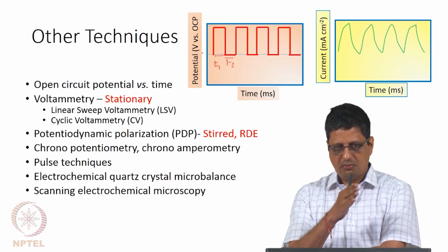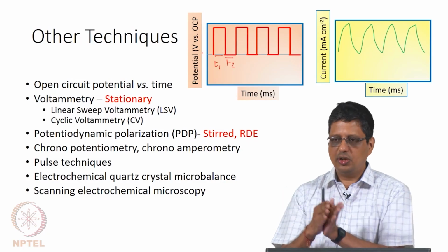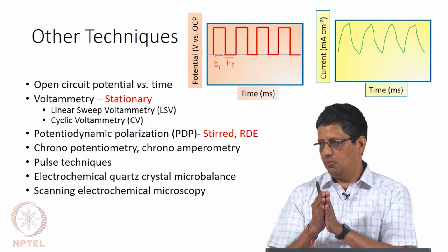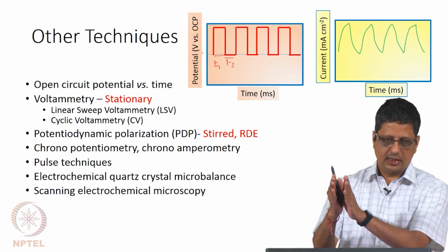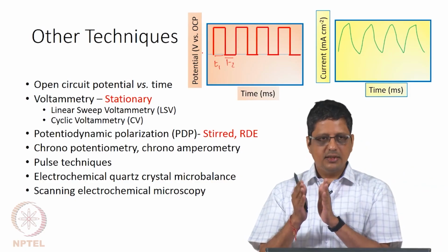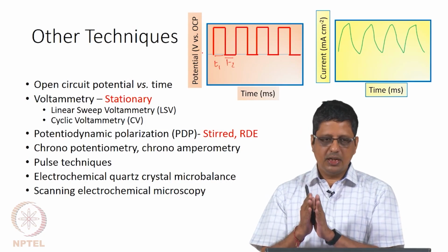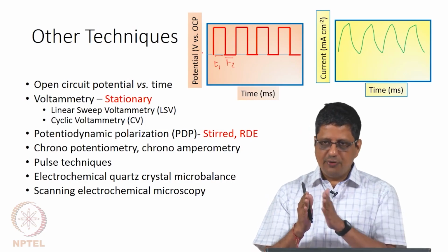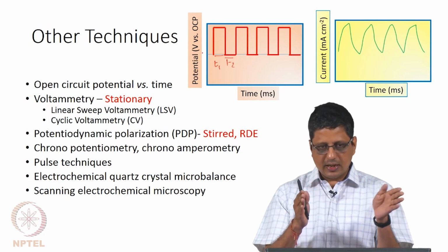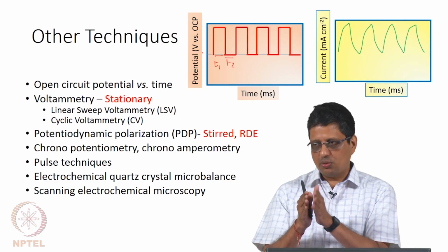Normally, when we want to deposit a material to some thickness, we want to finish it fast and then move on to the next sample. But the quality of the deposit may not be good. You can run it at a constant potential, or at a constant current. In both cases, many times you would get sufficiently good quality, and it is fine. Sometimes you may not get good quality because diffusion may be slow. So, deposit something, then give a pause for the material to arrive by diffusion, and deposit again, that is one way.